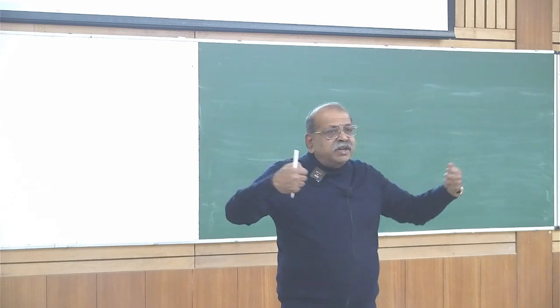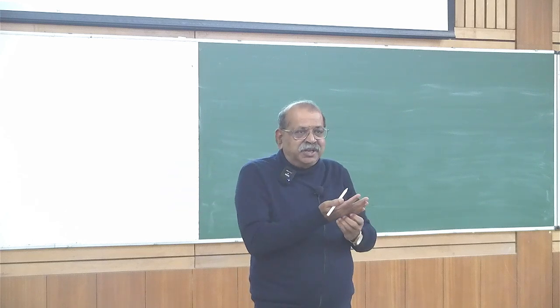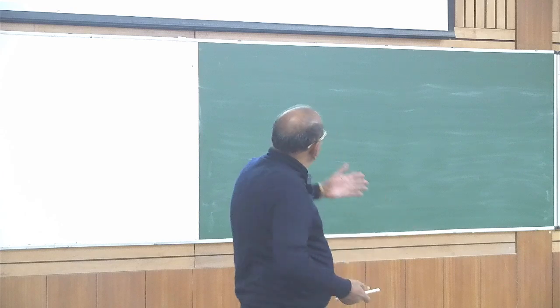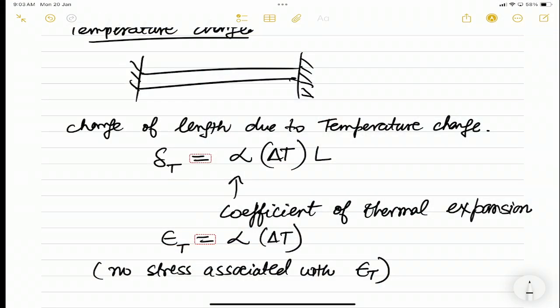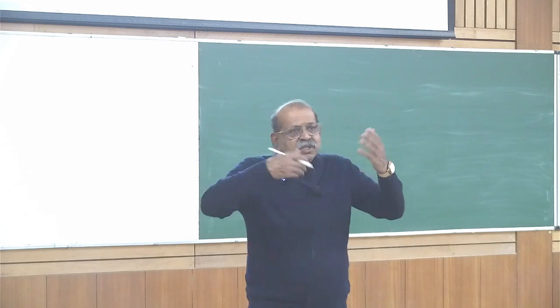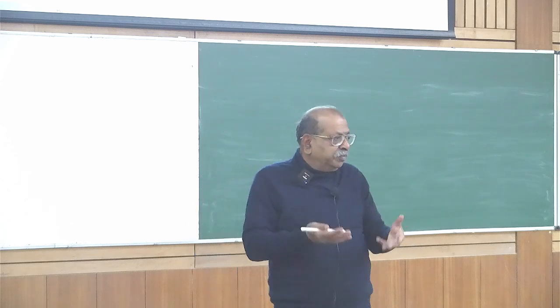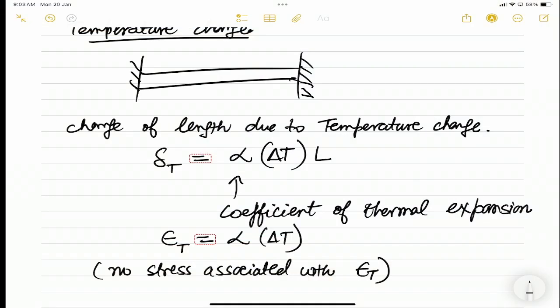And because of the stress, you can think of what is the load P which is coming in because of the heat. And that load we will get from the relation delta is equal to PL upon A. So because delta is not allowed to change, whatever this delta is coming will be equal to PL upon A. So you can relate this.